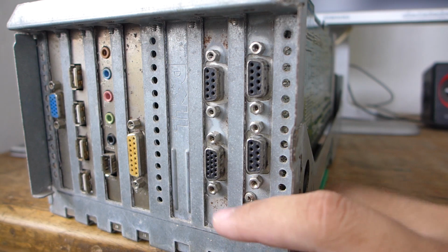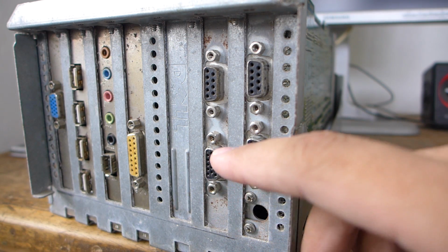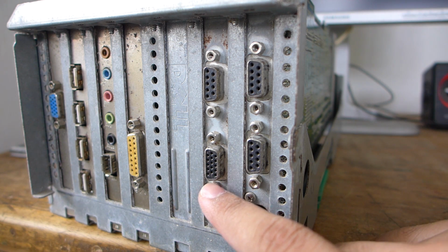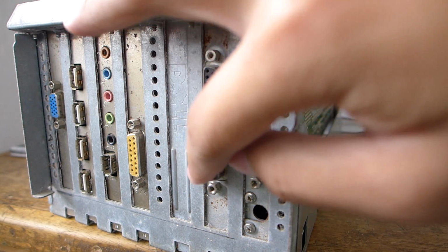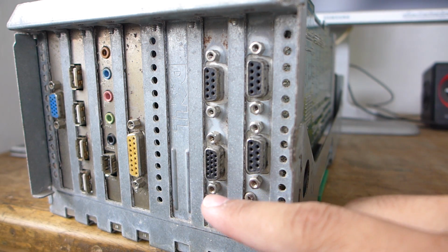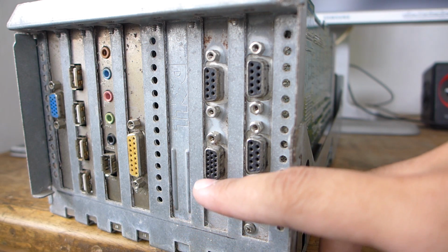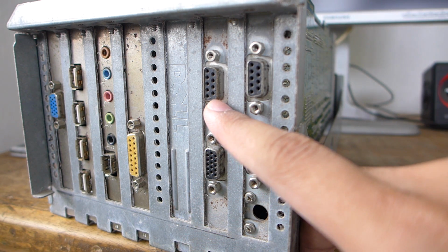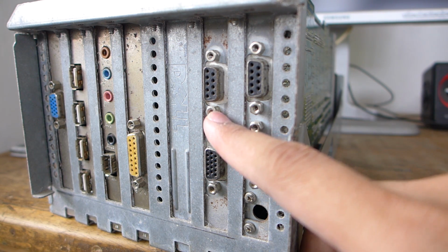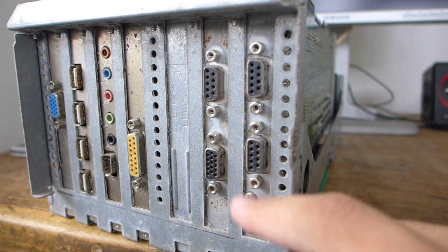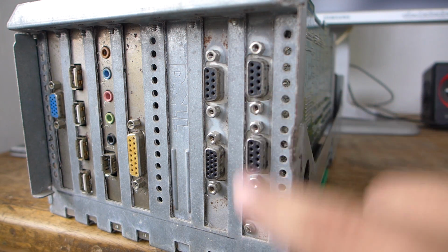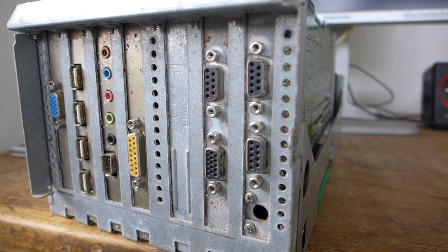So this port here is your multi-AV out. It may be using a DB15 connector, the same as a VGA, but this is not VGA. I don't recommend plugging in a VGA monitor here, otherwise you might screw up the development boards, or you would screw up your monitor. And this one is the serial port, which runs at 3.3 volt TTL logic, same kind of logic used in the Raspberry Pi. And these two ports are your controller ports. I think this one is controller 1 or this one, I'm not sure. I think I gotta label them at some point.